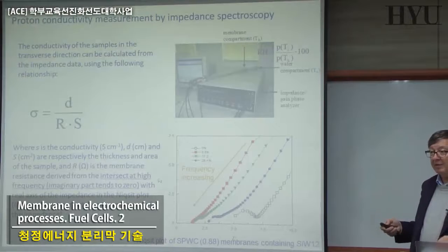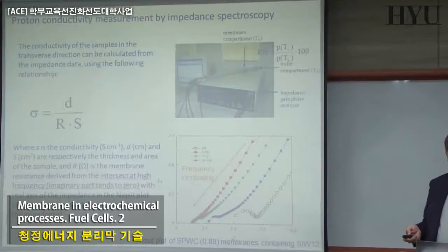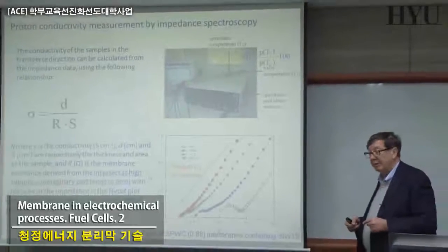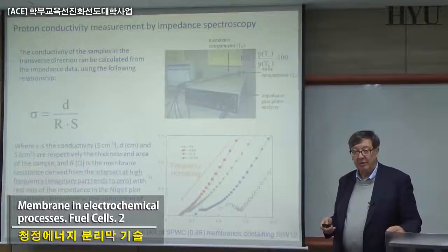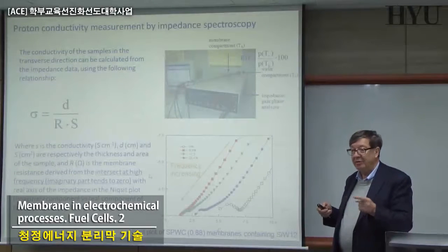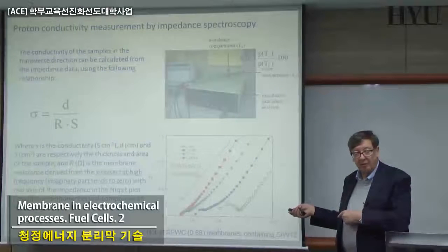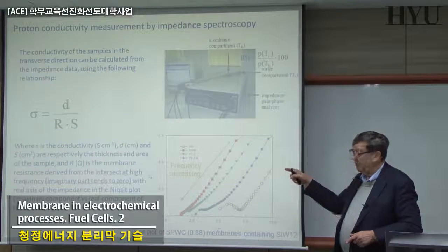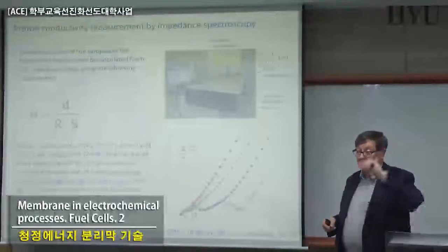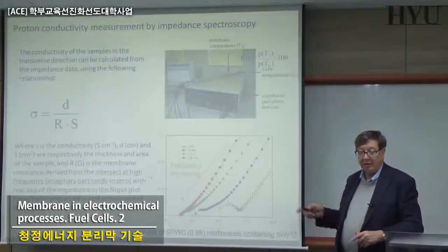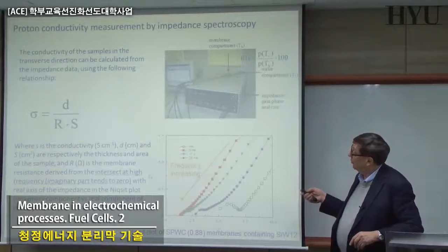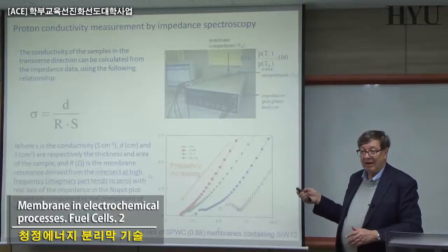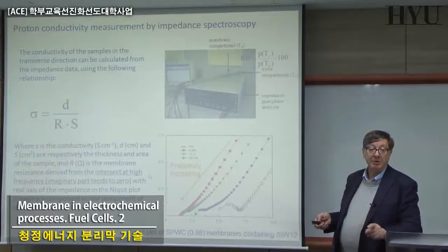Today, some of you are also experts, you can do a little bit better than this, and that is necessary because we have been learning that in this system, the ion conductivity can be apparently different, not because the membrane is different, but because other problems take place in the system. This problem, exactly like the one we were talking about before with going up and down with relative humidity, can affect the final performance. So instead of working with traditional direct current, applying Ohm's law, you can work with impedance spectroscopy.